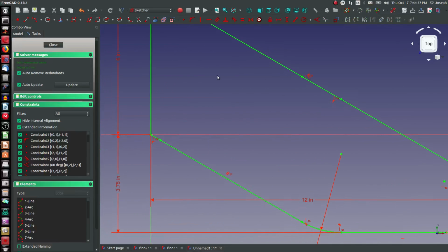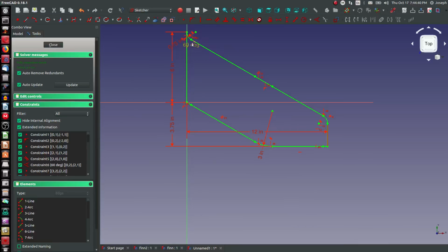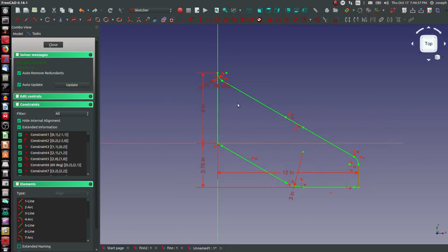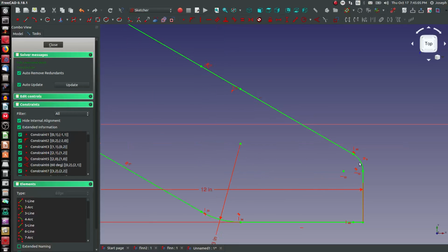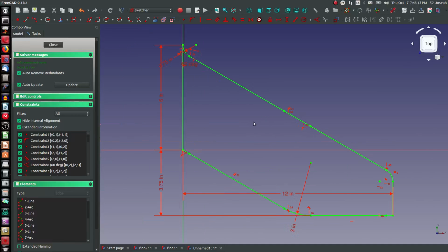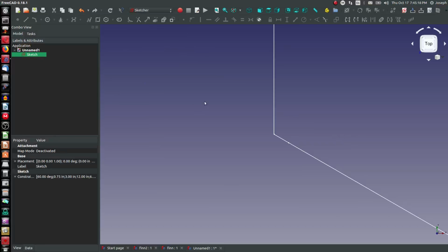Boom. Alright, so I got a point here, point here, point here, and so on. With every point I have on the top profile, I've got a corresponding point on the bottom profile, and they are vertical. The better definition that you want, put more points here, especially along curves. It really wouldn't hurt if you wanted a really high definition wing to put 1 or 2 points on every arc. I'm not going to go to that level of granularity because that will take way too much time and I will completely bore you.